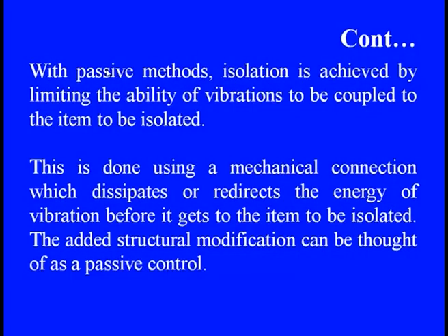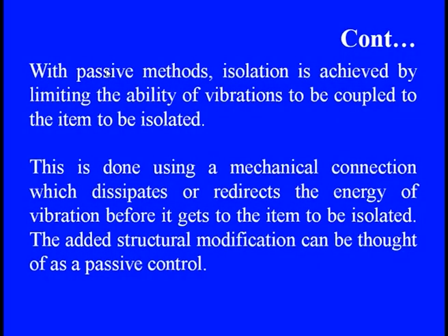So whether we are going towards the passive or the active, we need to first see the feasibility, what exactly the kind of excitation level is, and what the entire structure is, because ultimately the structure is supporting these vibration features and the sound propagation. So with this passive method, the isolation can be straightway achieved by putting certain isolators, but the basic limitation is what type of isolator we need to provide to cancel out these unwanted forces. Generally we need to see what exactly the connection is which we can provide from the isolator to the excitation, so that whatever the dissipated or radiated form of the energy is coming out, it can be straightway absorbed.